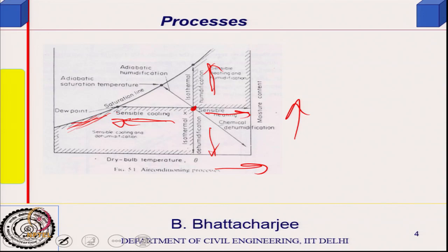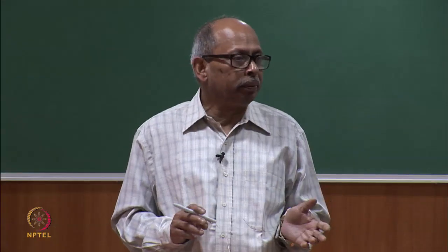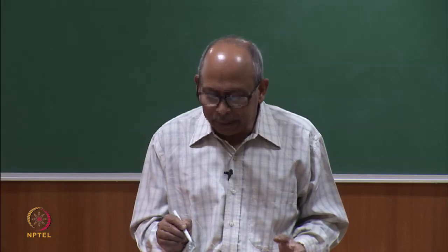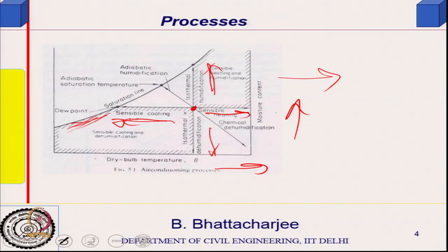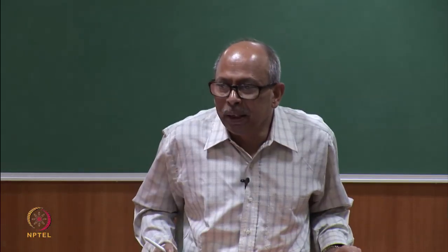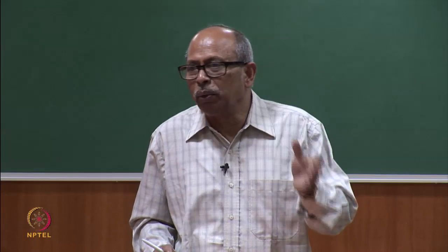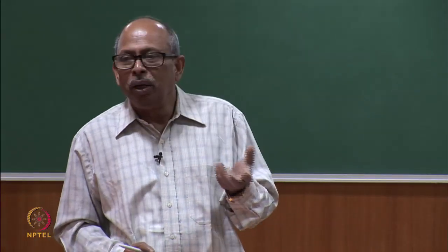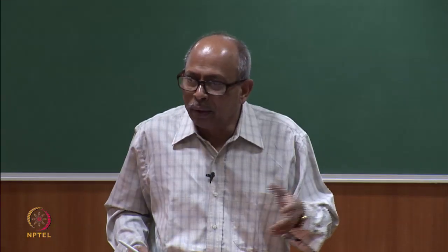Now, supposing I am cooling it, say the example is a desert cooler. Now, in a desert cooler, what happens? Air enters through a filter, where water percolates from the top, right. So, air enters in this manner, and it is dry air. Usually it is effective only in dry summer. A desert cooler is not effective in coastal areas. In the coastal area of India a desert cooler does not work, while in northern India or Rajasthan, etc., it still works.